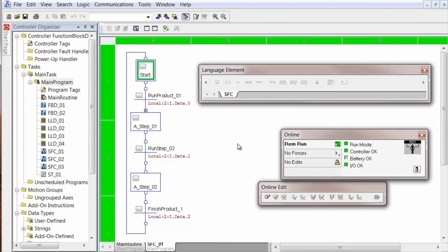It sets right there on start. It doesn't look at step 1 and step 2. It's not like RSLogix. So this would be analogous to running the main routine in an RSLogix diagram program. And then you have permissives, conditions, on the rungs to jump to a subroutine. And once it runs that subroutine, it comes back to the main routine.